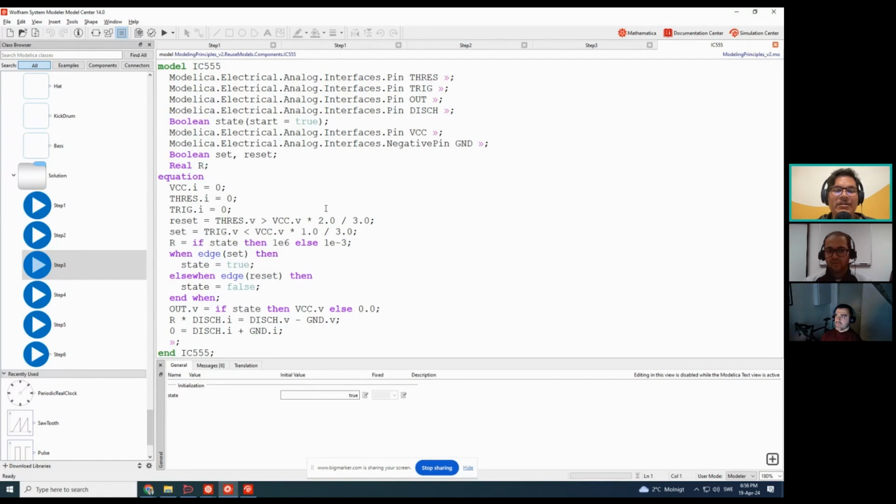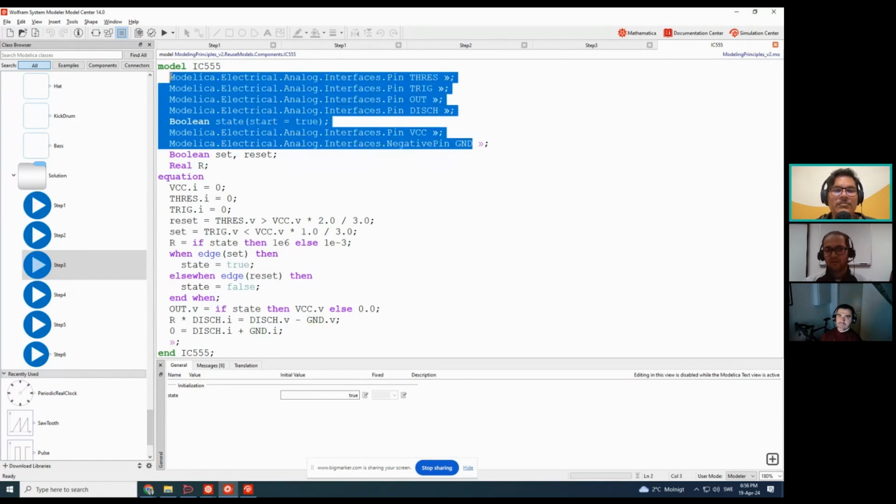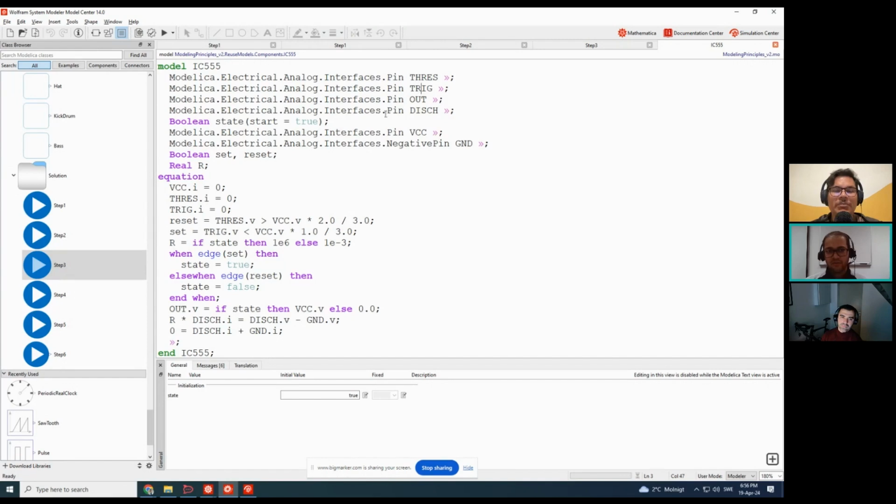Right. So basically, you have defined which components are needed, and the inputs and outputs, and for those inputs and outputs, based on the different states, you are creating your own triangular wave or timer, right? And this is something that you created custom because you had a custom need for it. Yes, this component didn't exist in the Modelica library, so I made it. And the thing is, you made the component once and it has been several years and you have been reusing it, and we have been taking advantage of that and reusing it in our course as well.